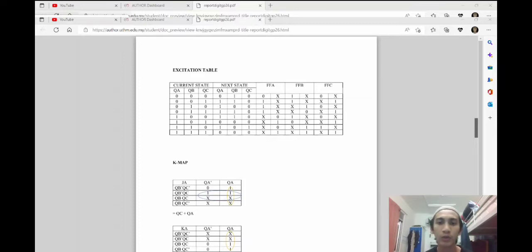Okay, first we go to flip-flop A. For JA, we have 0, 1, 1, 1, X, X, X, X. For KA, we have X, X, X, X, 0, 1, 0, 1. For flip-flop B, the JB, we have 1, 1, X, X, 1, 0, X, X. For KB, X, X, 1, 0, X, X, 1, 1.